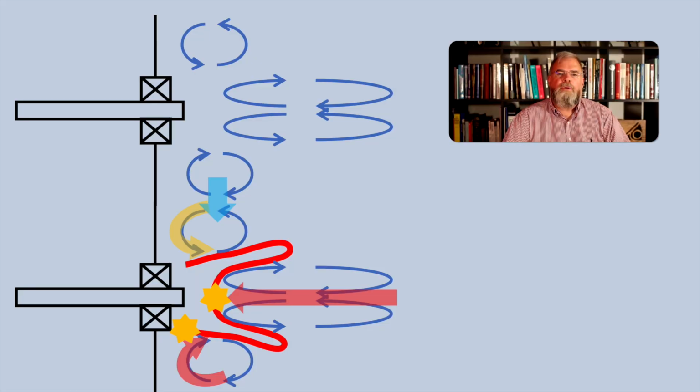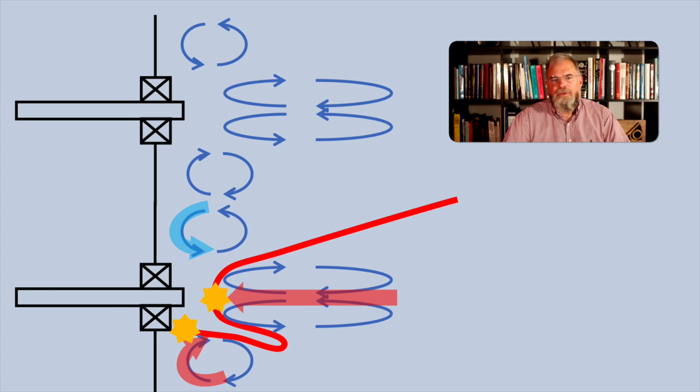If this temperature is reduced enough, this flow will no longer be hot enough to ignite the fresh mixture on this side of the burner, which is still on, and the flame will detach. The fuel-air mixture on this side of the burner will burn much slower, and it will be consumed eventually by the spreading of the remaining stable portions of the flame.